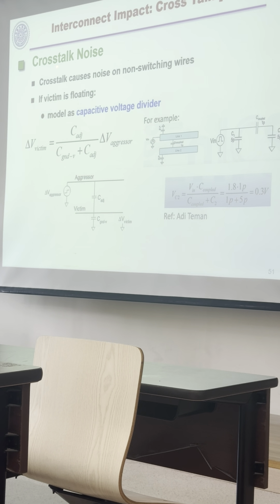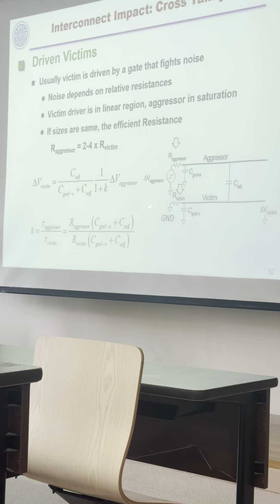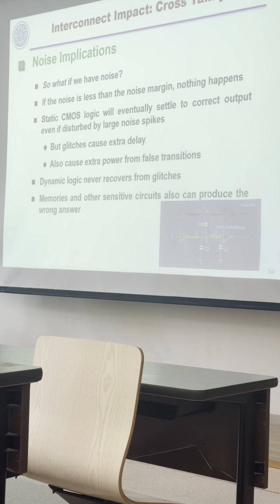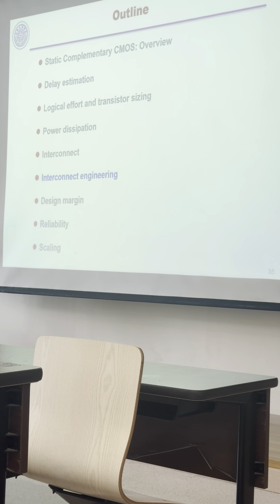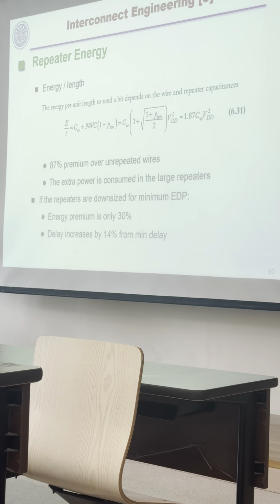If we want to solve this crosstalk, we can minimize this junction capacitor, this adjacent capacitor, or make the driver's return resistor smaller here. This is a very general concept, not too difficult to remember. Okay, so these are the key points of lecture 9.